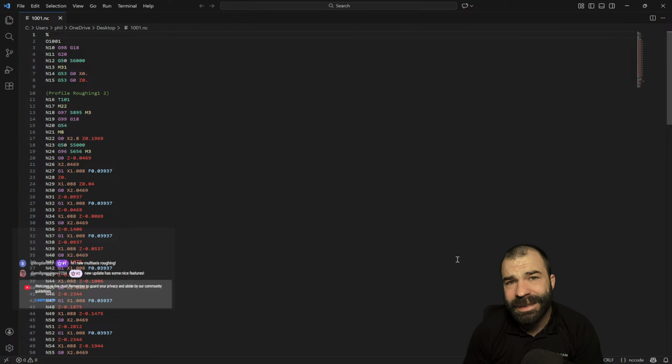Now on a Haas TL series, you could have a tool changer or you could have a tool post, one of which is going to require you to do certain things here. But as you guys can see, I'm going to show this off real quick. The easiest way to look at this is we are working with X positive, and we're working closer to center line, which is 0, which means X starts large and goes to 0. So a positive large value back to 0. So we're basically moving X negative.